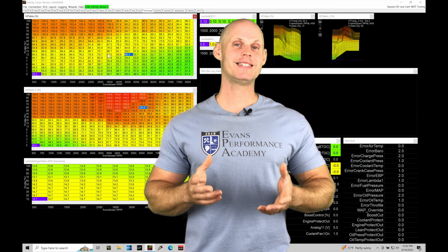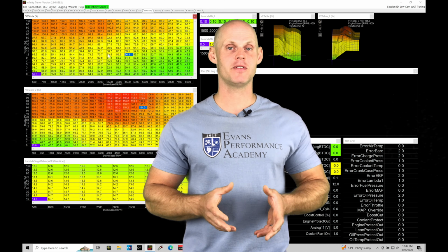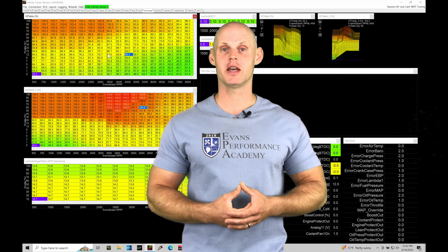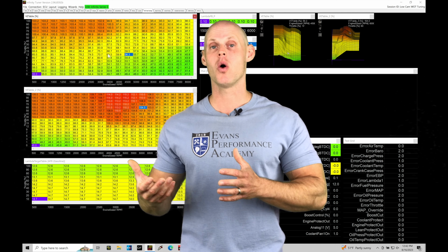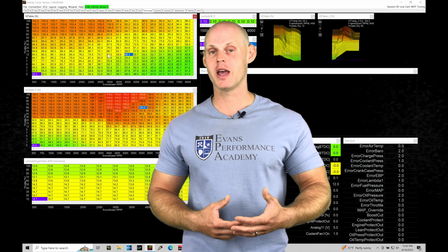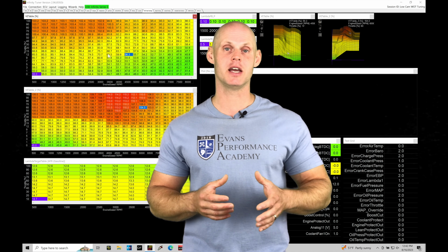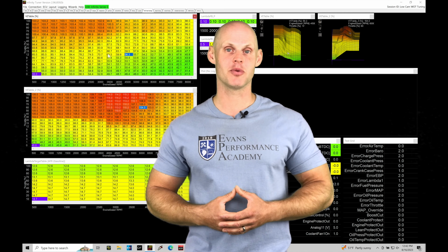Welcome back to part 6 of our live training session here with our Honda K-Series engine and AEM Infinity. In this training module, we're going to be taking a look at completing the calibration process, dialing in our high cam or VTEC operation. So looking at our fuel, spark timing, and variable cam control, as well as setting our VTEC engagement point. We have a lot of things to discuss. Let's jump in so we can check out this tuning process.